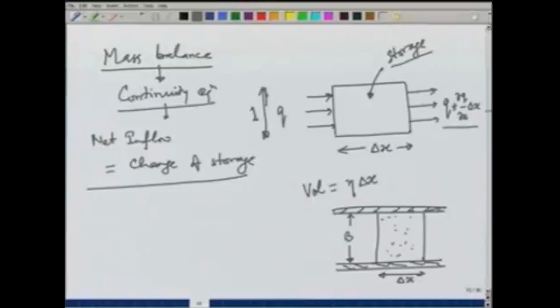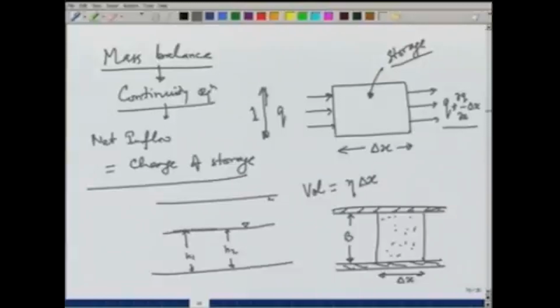Since there is no change in the volume, you can compare this case with an unconfined aquifer, in which case, suppose you are pumping water from this aquifer, with time the water level will go down, or in case you have a well here, it may go down as this, but the area or the volume is changing with time.